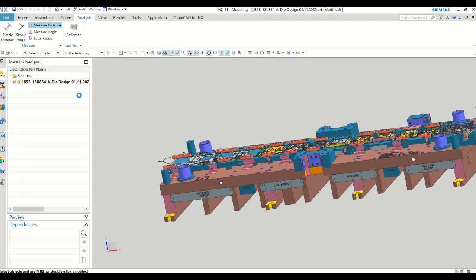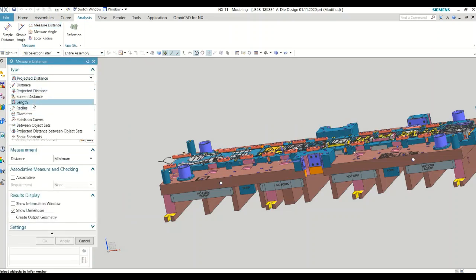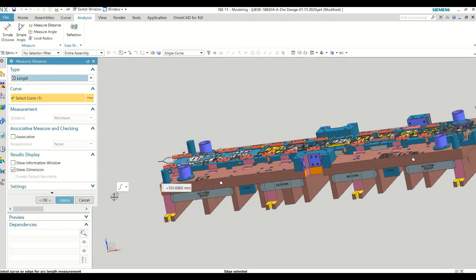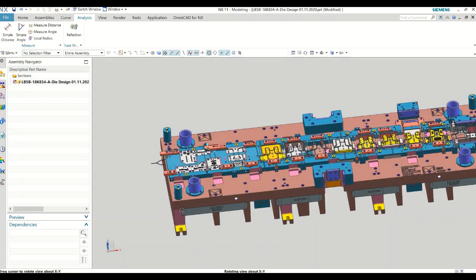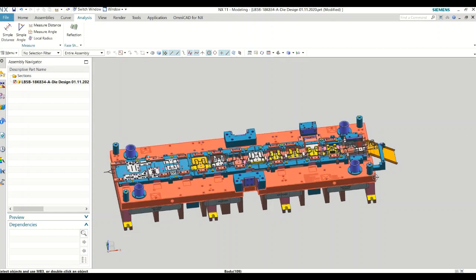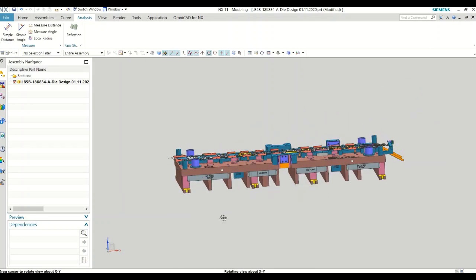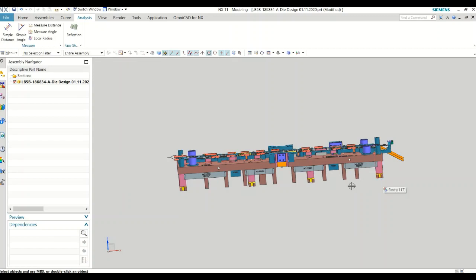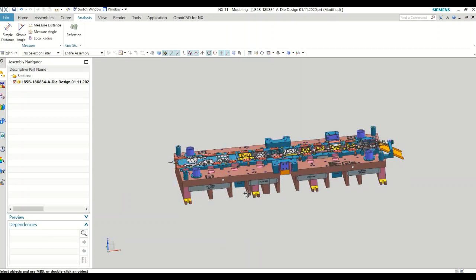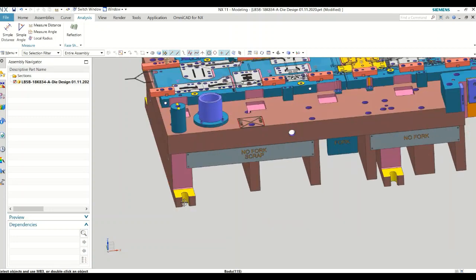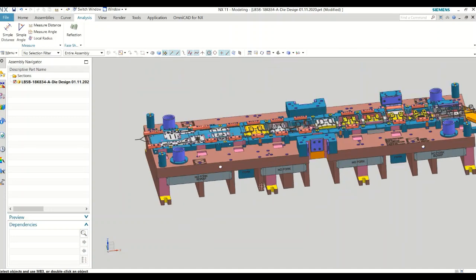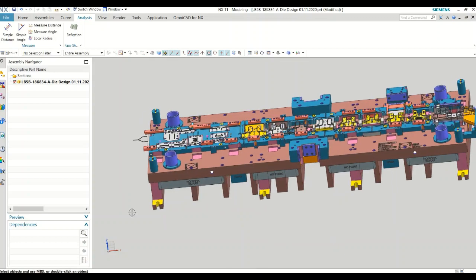Let me check that. Yes, it's 4 inches, and the rest of that gap we filled with parallels. It saved our material and machining. Wherever we have a clamping slot, that's a clamping parallel, and otherwise a normal parallel. All of them are lower parallels.